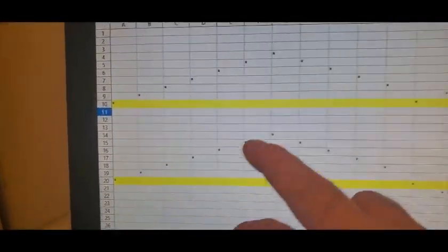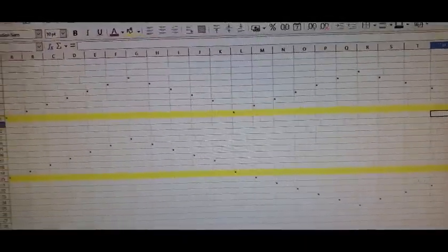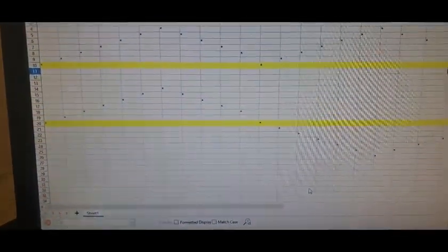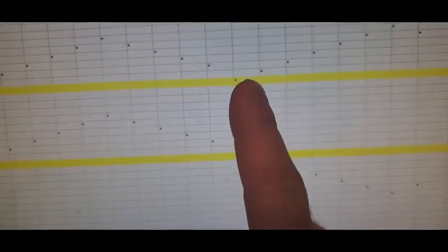You would only be able to rectify this part, but this part's the wrong voltage for it to be able to rectify it with a single diode. Now the second thing, and I'm not going to confirm this today. When we start running this as a bipolar machine, I'll confirm it. But it seems pretty clear also, if you just have a single diode, this is going to be a dead short. So that's not going to help you.